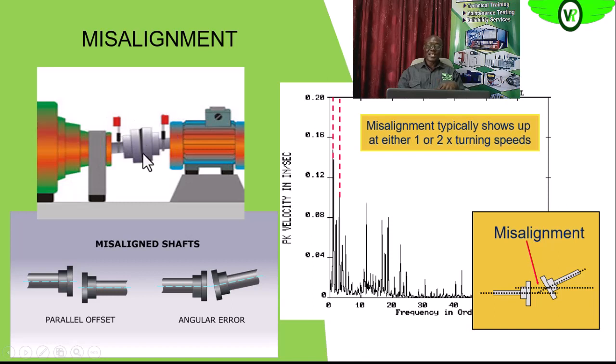If this kind of misalignment is in the system, in addition to the load, the motor will need to overcome that misalignment force around that coupling. So that misalignment force and the load that we are driving will mean more requirement on the electric motor system, which means that we will be overloading.